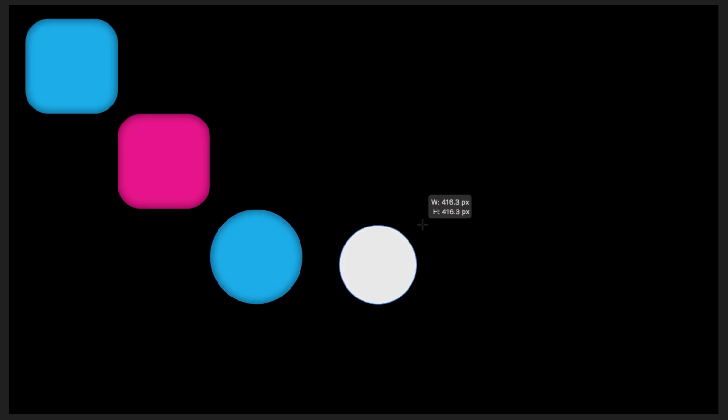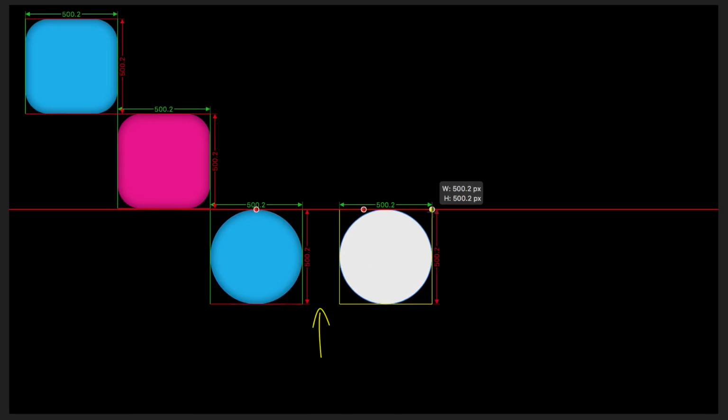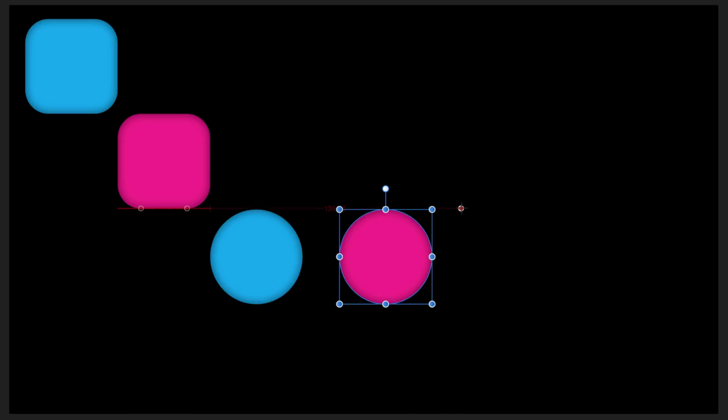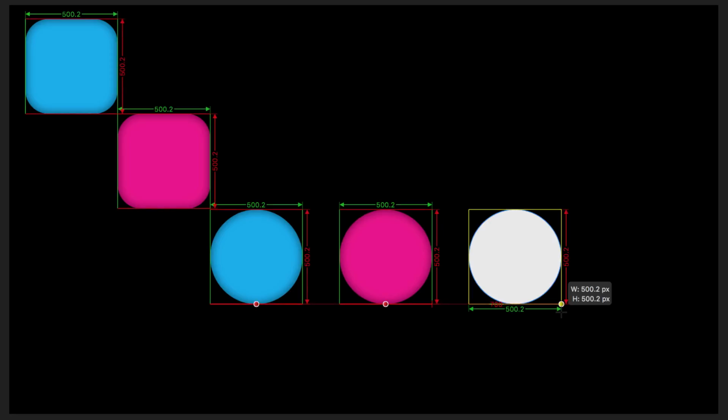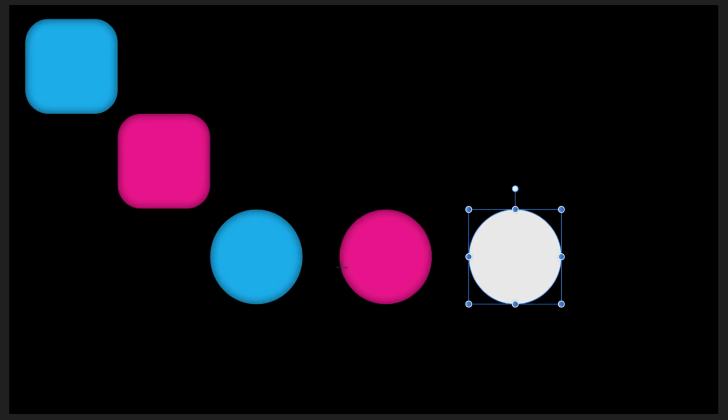using snapping. If your cursor is only aligned in one direction, you will receive a readout of the distance between the cursor and the shape causing the snap. Once I've drawn another shape and established a gap, Designer will now include this gap in its snapping calculations. So I can draw yet another shape which is exactly the same distance from the blue and pink circles.